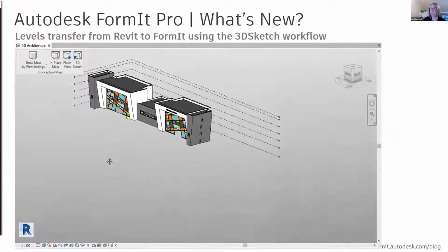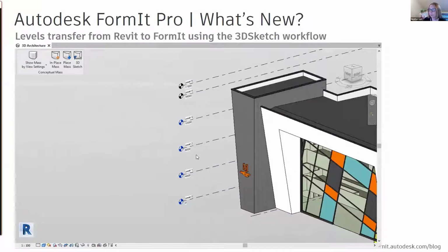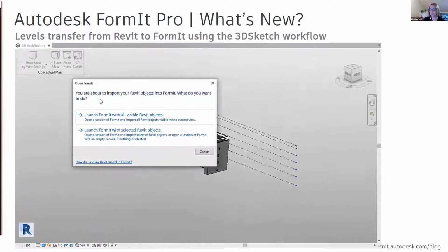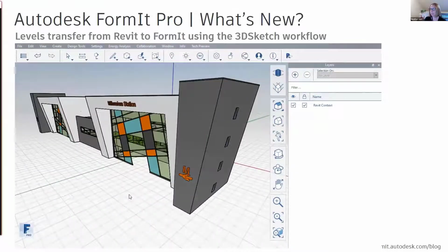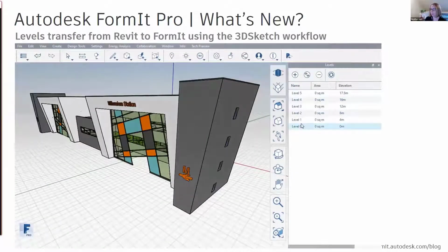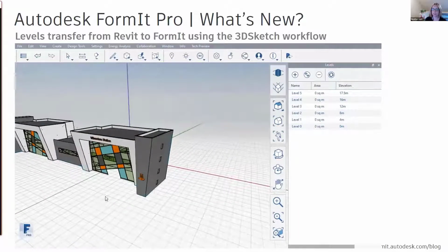So here in the Revit 3D view, you'll see we have some layers that are levels that are visible here. So now when you click on that 3D sketch button from the Massing and Site tab and you launch FormIt, in the levels palette of FormIt, you now have all of the Revit levels right there with the elevations all set up.